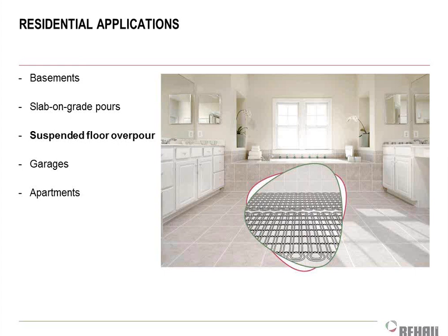And that foil facing reflects the radiant heat back up. It'd kind of be like standing out in the sun and having a mirror and using that mirror to redirect the heat somewhere, right? Like when you were a kid, you probably directed it on leaves and started fires because you were a hooligan, right? Same kind of thing here. The foil facing reflects the heat back upward towards my building or towards my house. So if you're going to put it on the ground, meaning basement or slab on grade, you got to insulate underneath for it to go up.